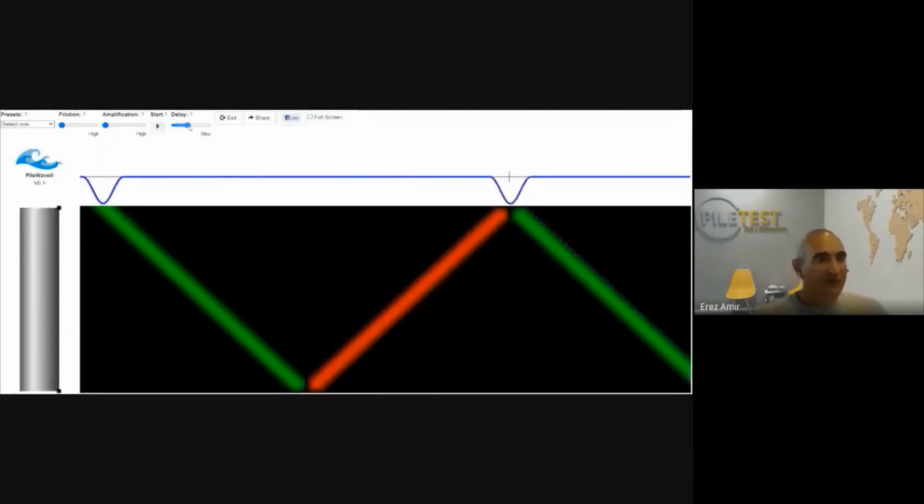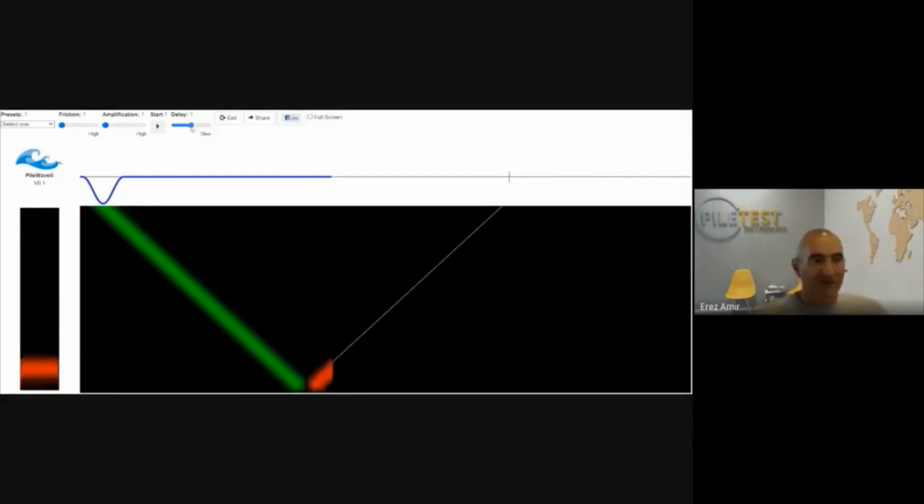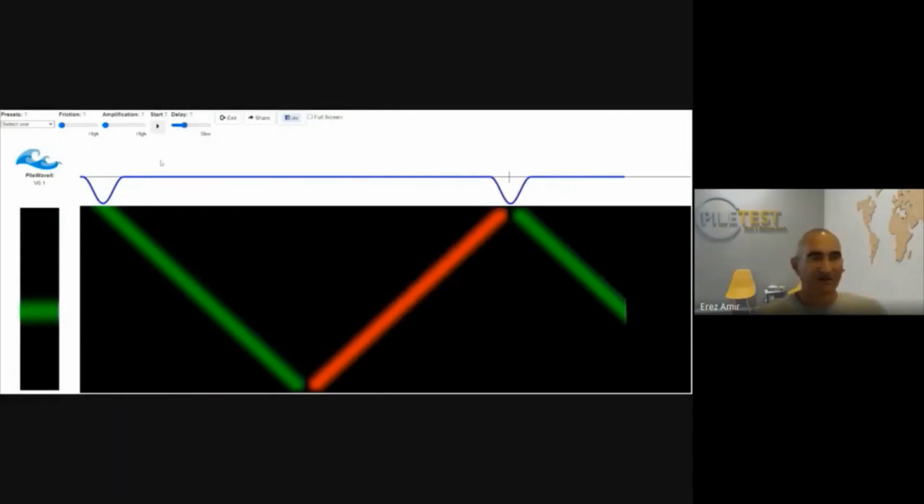let's do that with some delay. Okay, so this is the hammer impact, and a compressive wave is traveling down the pile. The wave keeps on traveling until it reaches the bottom of the pile. At this stage, it is converted from a compression wave to a tensile wave, and then it reaches back the top of the pile, pulls it down again, and that's about it.